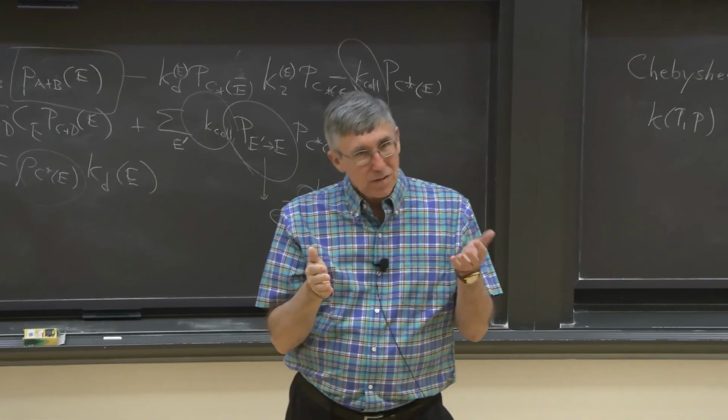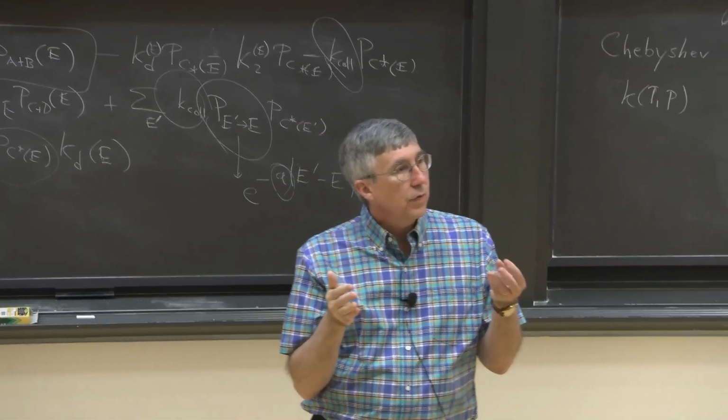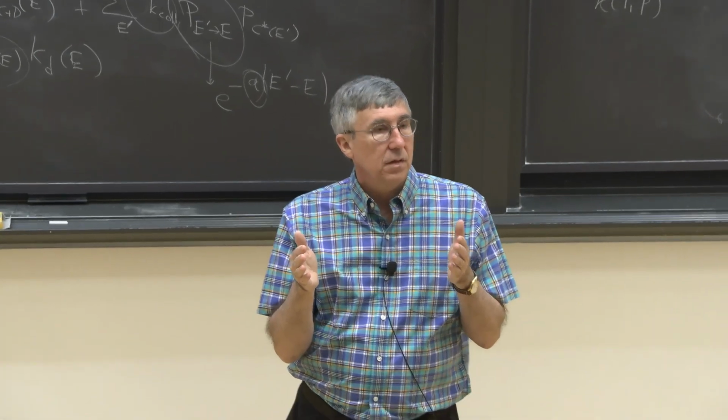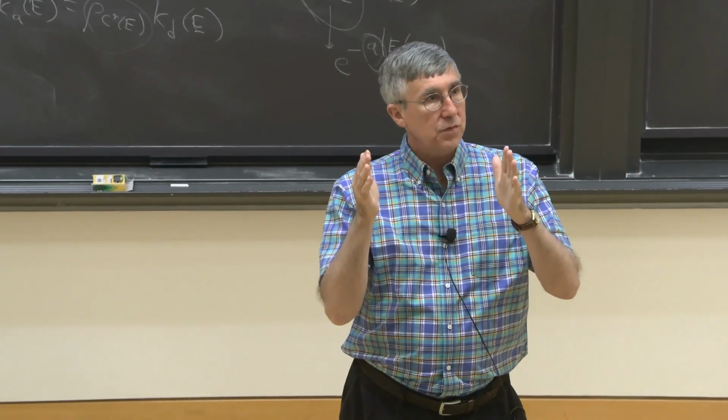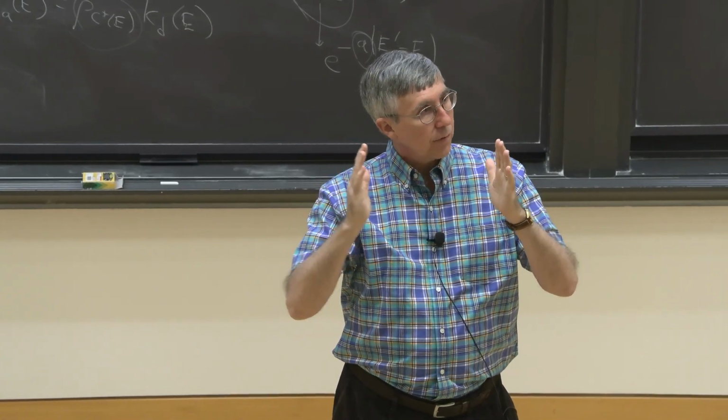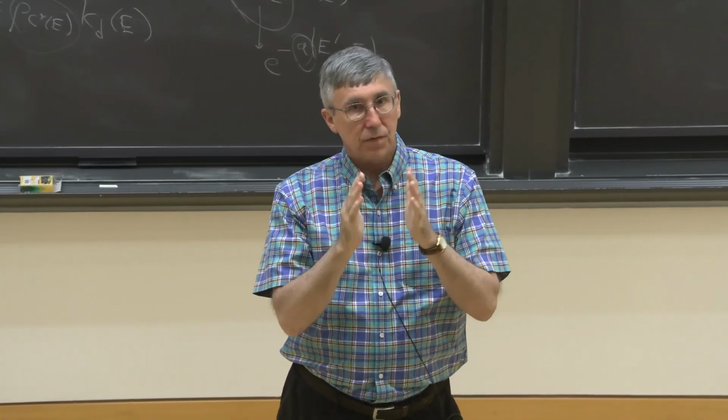Yeah, so the special engine that they use to do the octane number test uses a carburetor. So the fuel and the air are really perfectly mixed. So it's pretty much a perfect test where you close the valve and you're just compressing it, and there's not much of a physical delay.